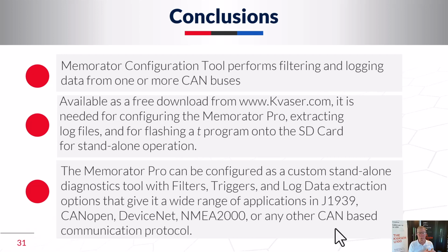I do most of my work with J1939 and NMEA 2000, but it's very powerful for anything, and protocols we don't even know about that have been defined by customers that run on our hardware. We deliver raw CAN data generally through the USB port in other ways, and so we don't get as much into the high-level protocols, although we understand them.